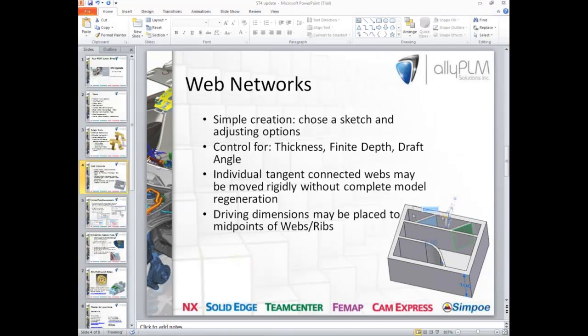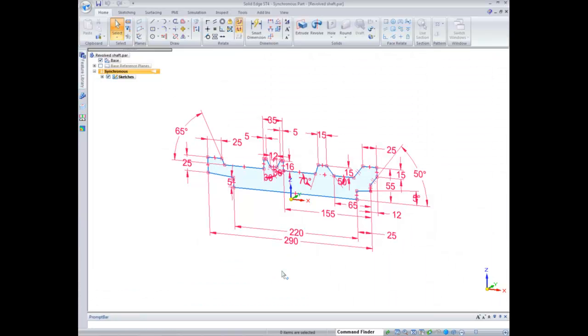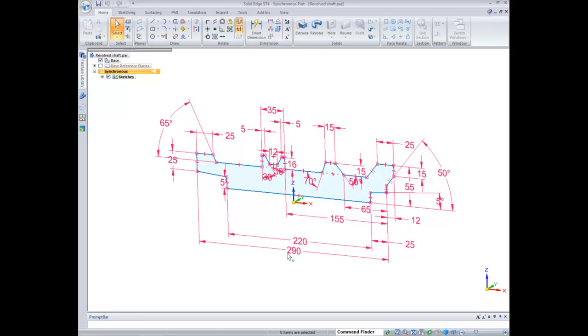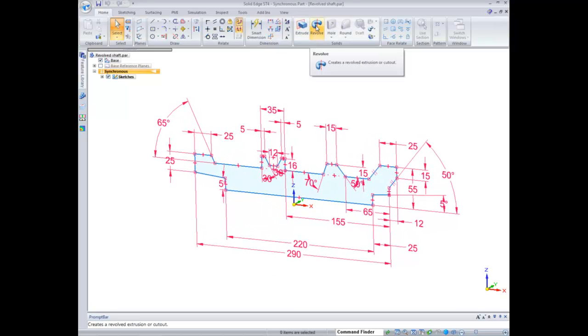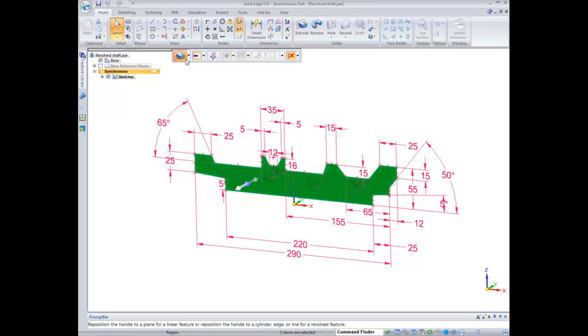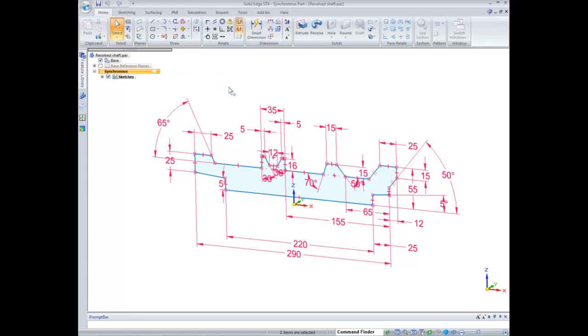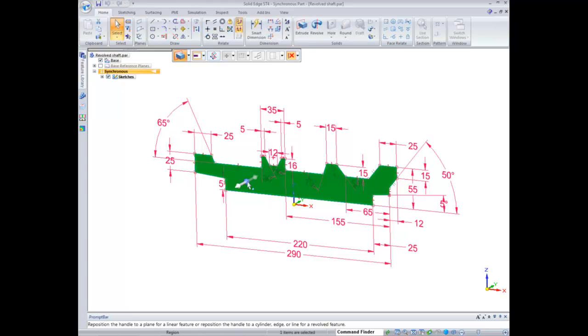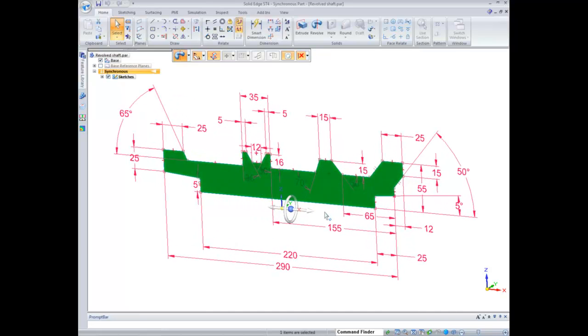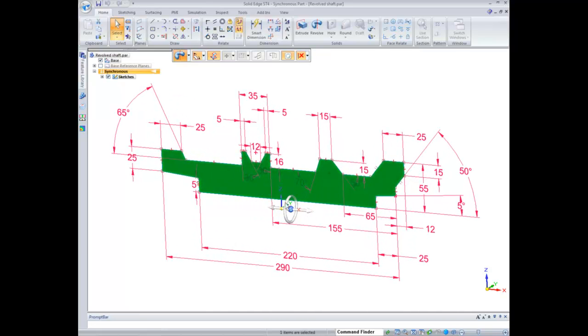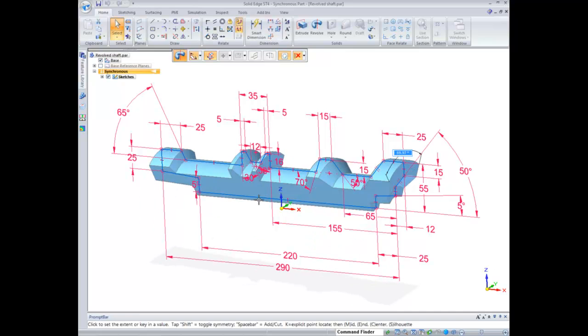So if we switch over to Solid Edge here, first thing I'm going to show you is a Revolve feature and live sections. So before, we would have had to use Revolve, or we could have grabbed the region and selected Revolve from the drop down here. But now in ST4, what we can do is grab the region, select that steering wheel, drag it down, and place it on an axis. And that'll change to a torus here, and we can grab that torus then and just revolve that feature around.